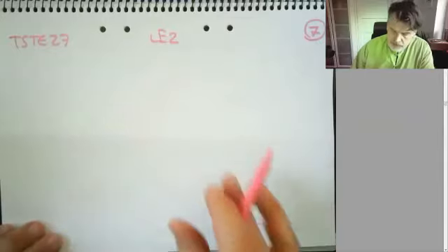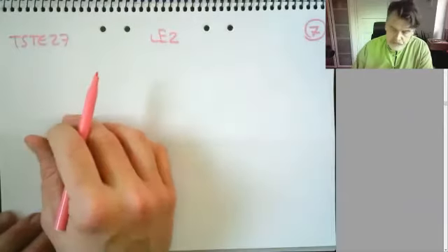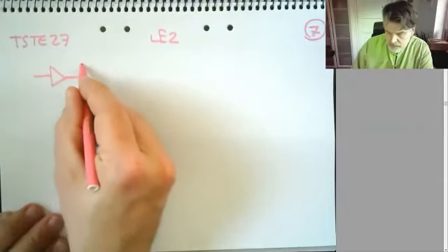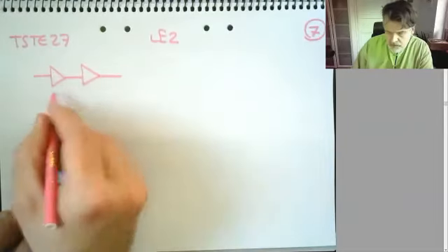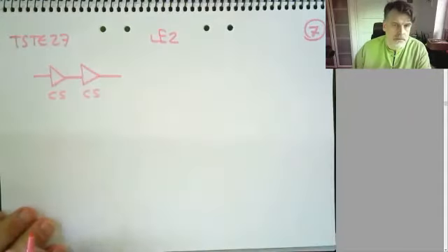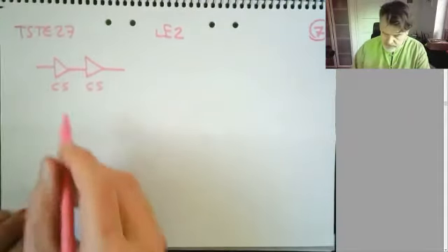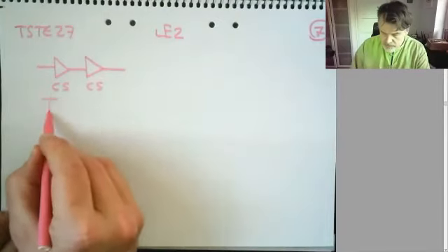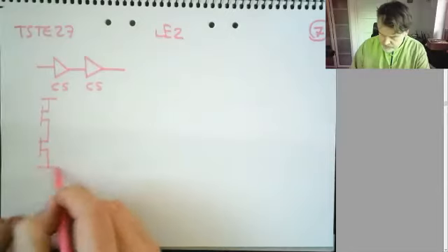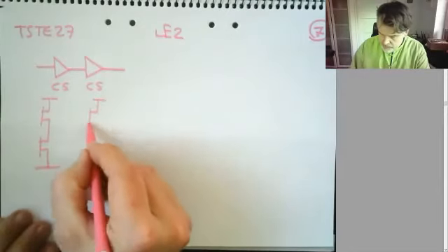We concluded we need higher gain. So what are the options? Well, perhaps quite obvious. I can take a common source, and connect that in series with a common source. So if I take two amplifiers like this, and from a transistor point of view, it could be done in many different ways. Well, not many, but 4 different ways.